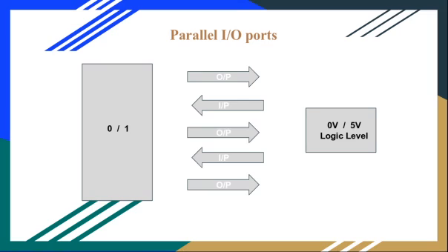So consider a reconfigurable port, as we have already seen that with Arduino there are 3 ports, B, C and D. In this port it can have 2 types of signals. We can have input, which is going to map or convert 0.0 volt to 0, or 5.0 volt to 1, that is a false or a true, or a low or a high.